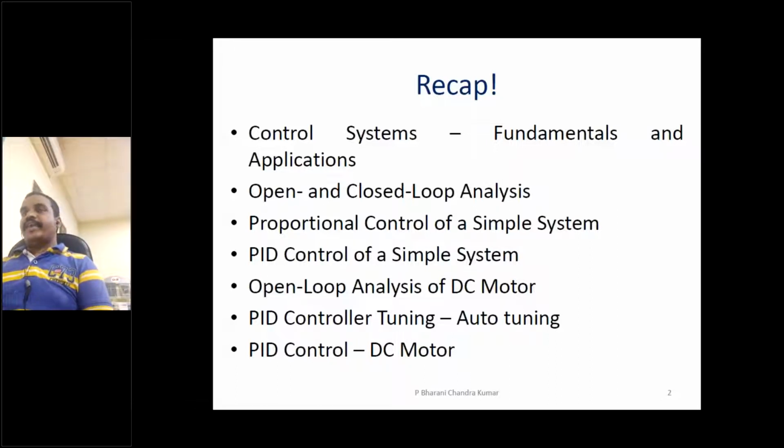Next we considered another plant, and we saw that if the plant doesn't have integral action on its own, then by using only the P controller, the proportional control, it is almost impossible to make the steady state error zero. For that purpose, we went for the PID controller.